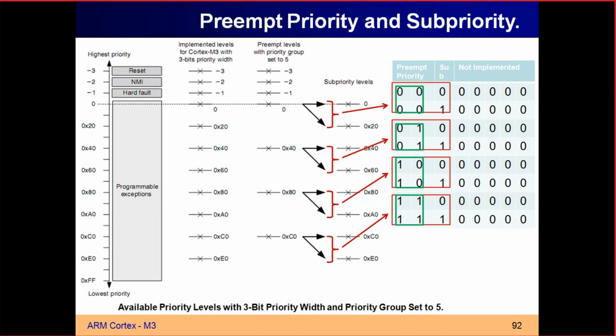I will be configuring only the interrupt numbers and priority numbers. I am not bothered about all these things. But you need to keep in mind, you need to check how many bits are implemented. Only that you need to keep in mind. The internal things, sub priority, preempt level, all those will be handled by the processor itself. We are trying to understand the operation done behind that.